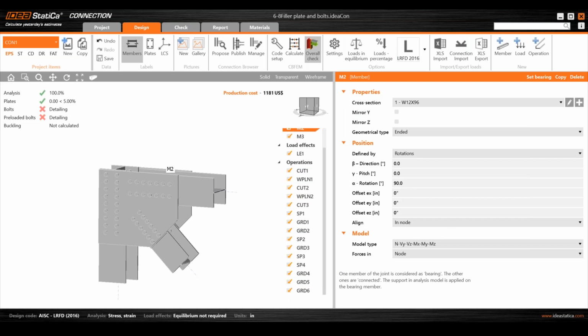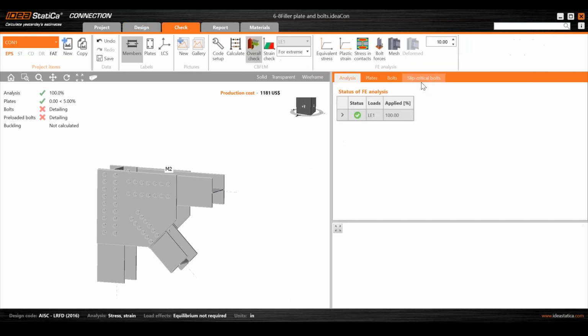There was a question about the K factor, the directional load factor for fillet welds, which should not be included for HSS connections. Currently they are, but we're working on removing them per the latest AISC code, 15th edition. We're working on removing them from our calculations. I mean, removing the directional load factor. The angle, right?